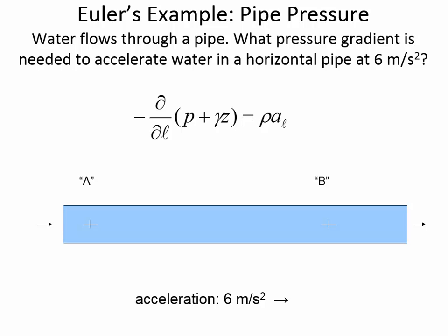All right. So how are the elevations different? Because we've got a z sub b term, a z sub a. Yeah, they have the same z. And so over here I'm going to write zb equals za. And doing that allows me to just cancel both of these terms out directly. So what I'm left with is p sub b minus pa is equal to negative delta x density acceleration in x. So already it's starting to look pretty good.